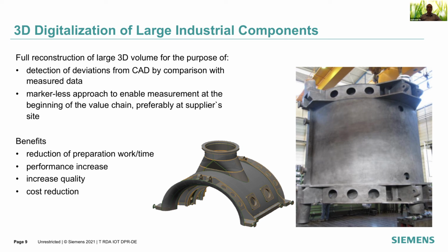The milling machine has to take some material from these oversized models, as shown in the slide. Then it has to be measured to see how much material was actually taken away compared to the CAD model, and then put into the machine again. This cyclical process is very important for quality control, and the deviation of the CAD model from the actual model is very important.